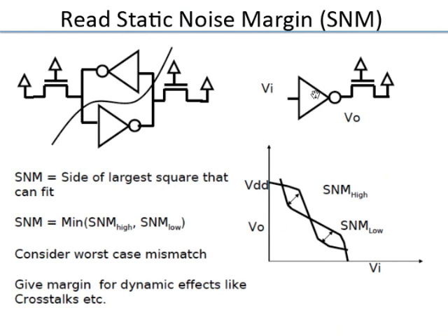Remember, when we change the strengths of the PMOS and NMOS relatively, what you're doing is you're skewing the transition. If you make the NMOS strong, what will happen is this will move to the left. Now it turns out that we'll see in the next lecture the PMOSs are made really weak. So these are really skewed inverters.